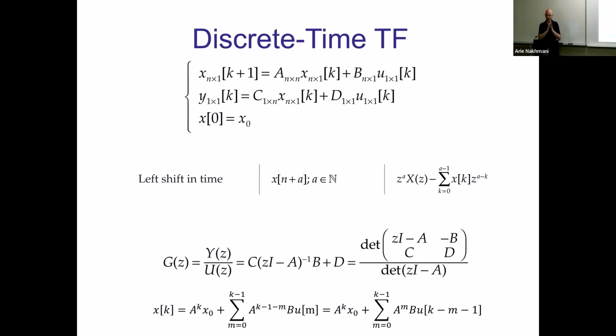So if these vectors are not spanning the entire space, you cannot get to some space, some particular axis ever, no matter what your inputs are. Is it clear where I'm going with that? So any reachable point in n-dimensional space that you can get to with your controls, with any control inputs, is spanned by these vectors, B, AB, A squared B, A cubed B, and so on. If you have some vector which is not a linear combination of these vectors, you cannot get there with any U. All right?